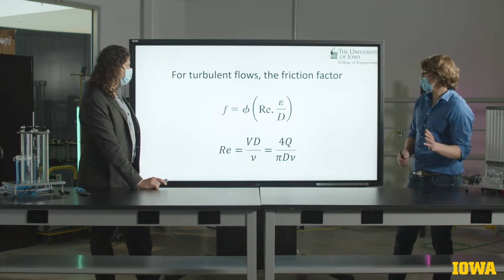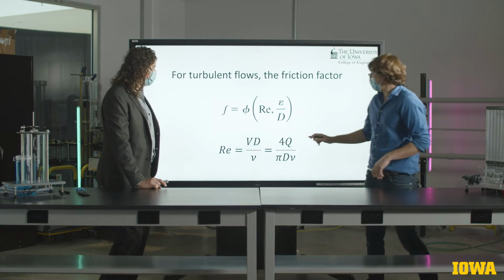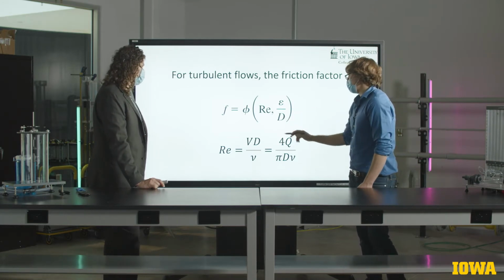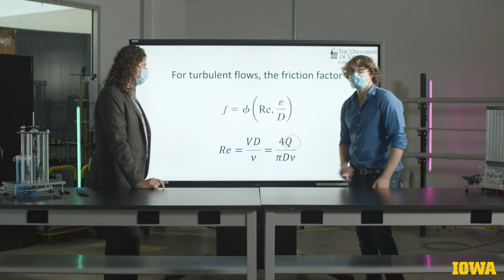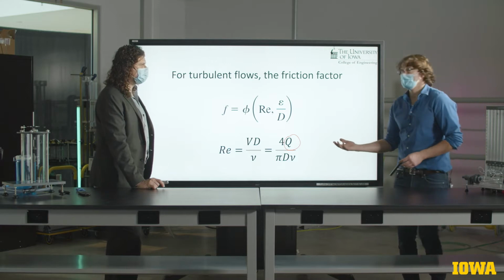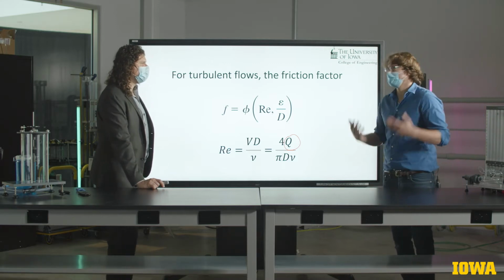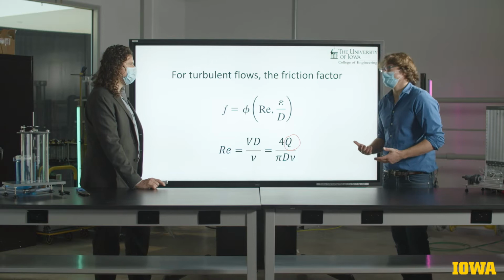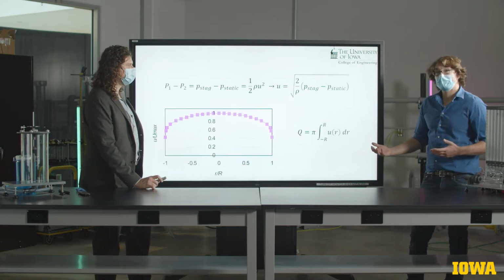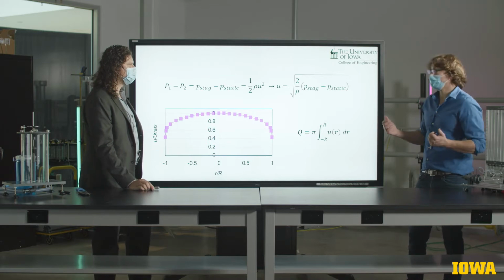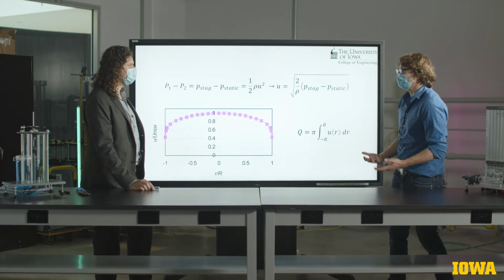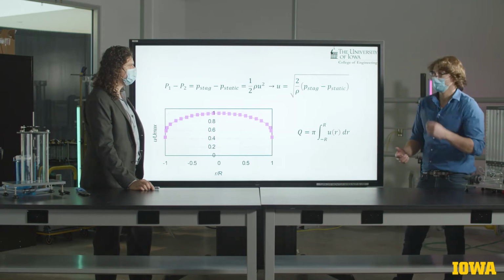That's right. And something to keep your eye on is that you'll notice that both in the expression on the last slide for f, as well as in our expression for the Reynolds number, we have the volumetric flow rate showing up, Q. Ordinarily, this is a quantity we'd get using that Venturi meter that we have installed in the pipe network. However, we're going to be taking a slightly different approach using the Pitot probe and the measured velocity distribution to actually manually calculate the volumetric flow rate leaving each pipe.